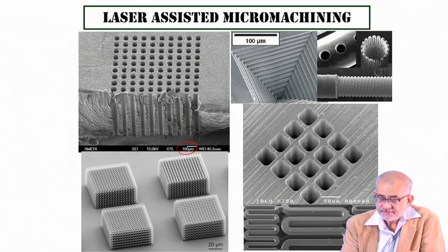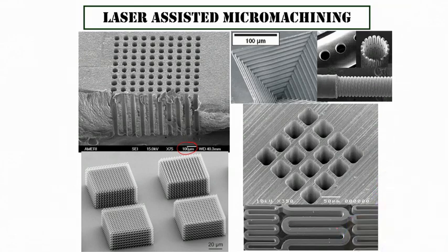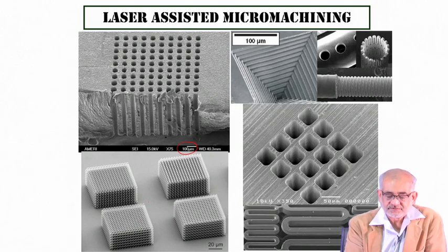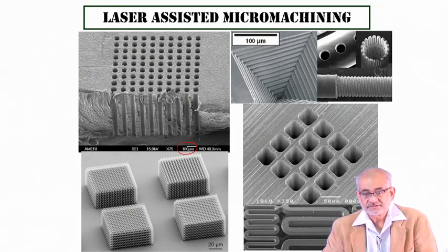One can also create such heat pipes or heat sinks, or certain features which will expose very high surface area for heat dissipation. You can even make such heat dissipation devices or heat exchangers where, because of the sharp features, any gas or air that passes through will be able to throw away heat much more efficiently through this kind of structure than in an otherwise solid structure.